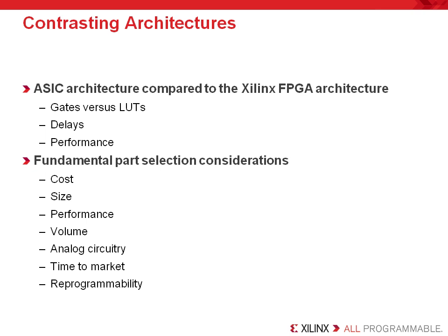Some customers still try to choose an FPGA by using a gate counting methodology. This is an inefficient process. We recommend building a sample design and just resynthesizing it for your chosen device family. Of course, you should use good HDL coding practices for optimum results. In general, gate counting methodologies for ASICs require extra gates for registers that are included with FPGAs. So choosing an FPGA by gates is often very misleading.